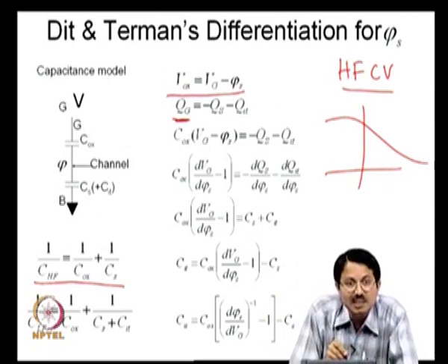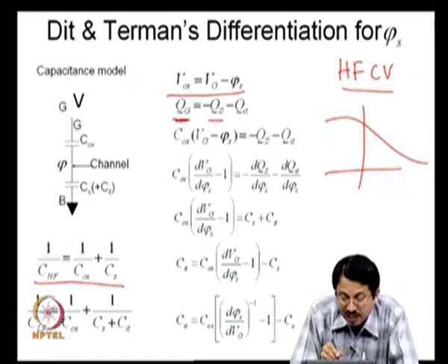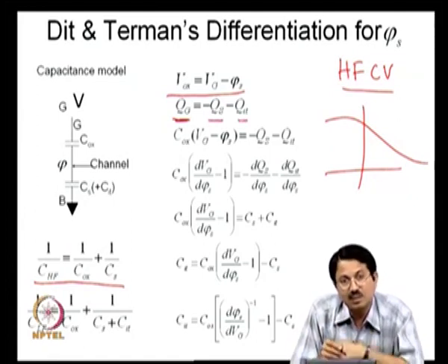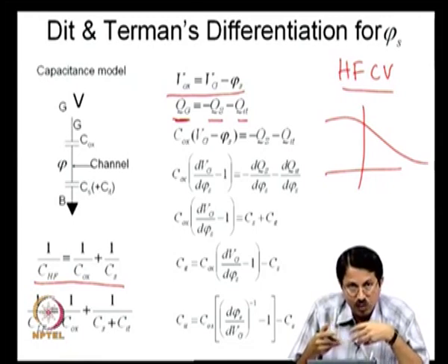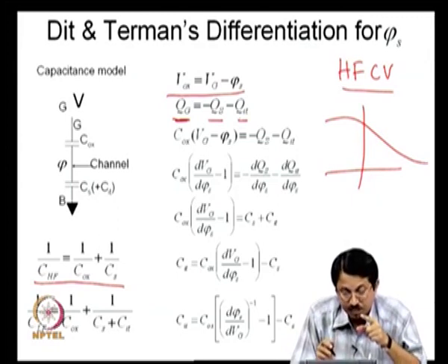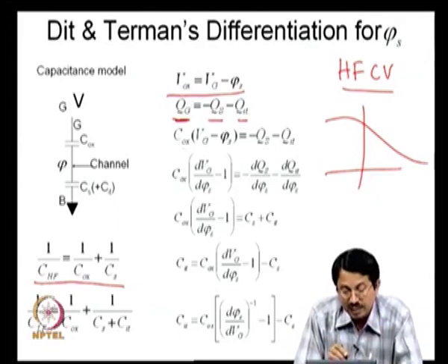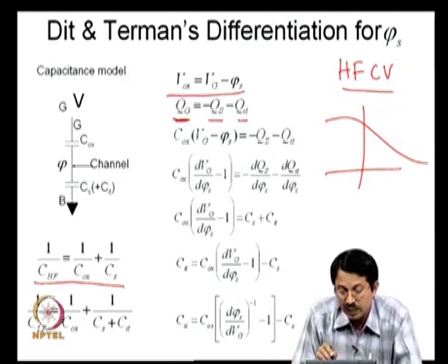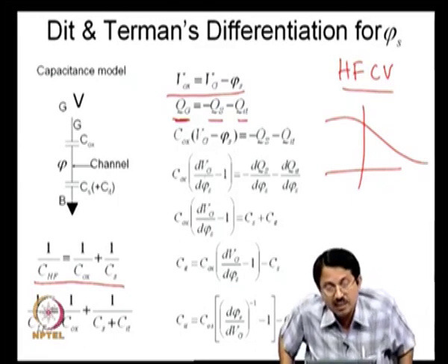So, the gate charge that is put is now Qs and Qit combined. Okay. Qs is a silicon charge which is essentially coming due to the ionized impurities and electrons, and Qit is an interface trap charge. And now hence I can write Vox is Qg over Cox, essentially Cox times Vg minus psi s, okay, and this essentially is Qs and Qit,